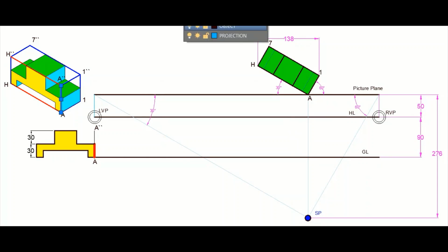So what we do, we just start with the first line, that is starting from A up to 8 double dash. So this line is 60 millimeters. So that is the height of the box. That is the maximum height of the box. Then next we connect the two vertices of this line to the two vanishing points on both the sides.